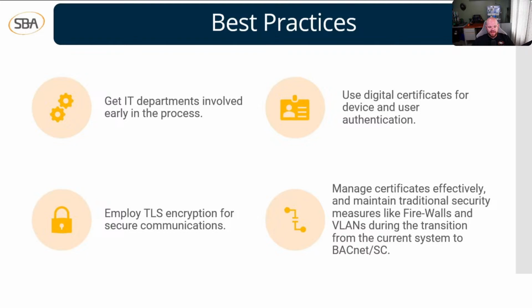The next thing is to use digital certificates for device and user authentication. Remember what I said. These aren't just controllers on BACnet SC. It can also be workstations. So we have to make sure that these certificates are set up for not only the devices but also for our workstations and any user accounts that are on those workstations as well.